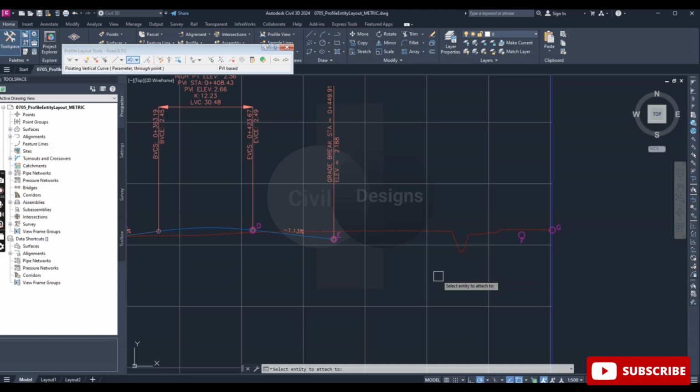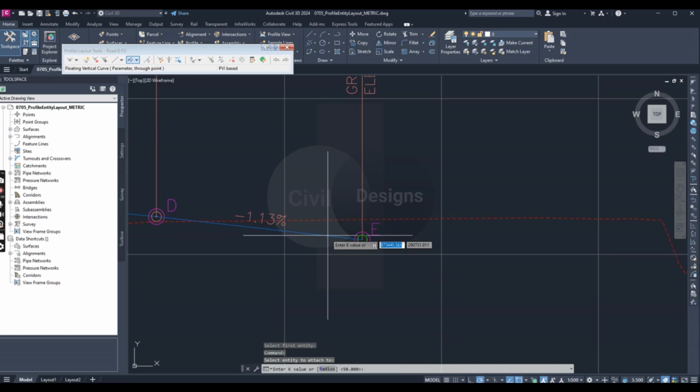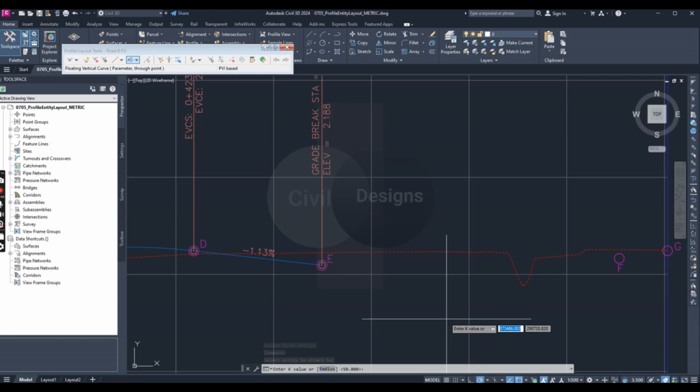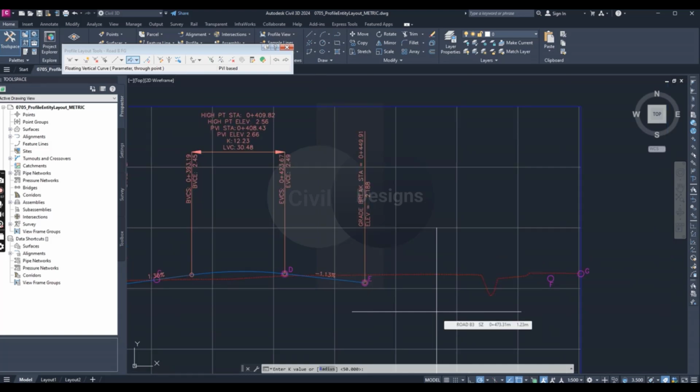At the select entity to attach prompt, select the tangent between D and E like this, and just remember to pick the tangent line and not the end circle. Also you have to select the tangent between the midpoint and the end point of the tangent at the circle labeled E. Selecting too close to the end point at the circle labeled E will give a result of end of selected entity already has an attachment, so be careful about that.